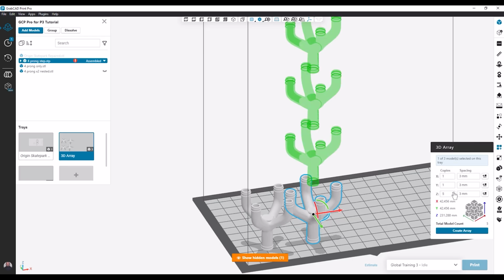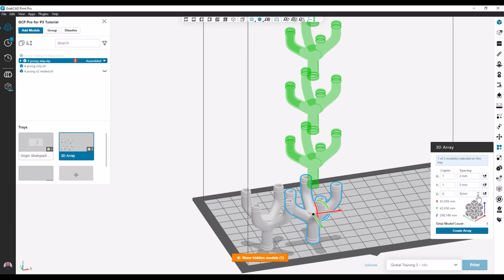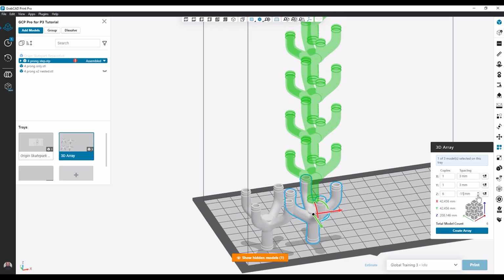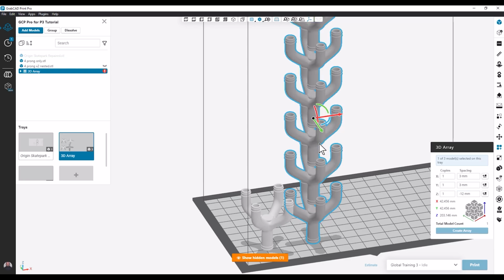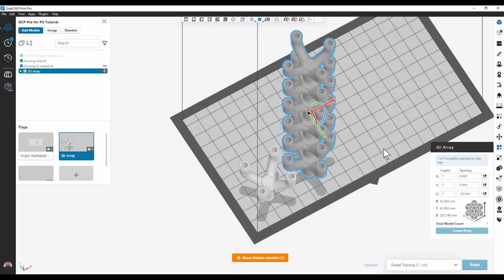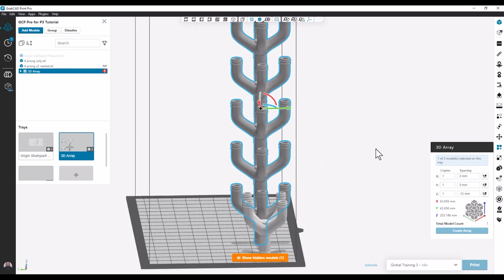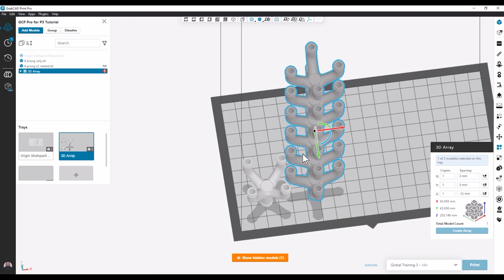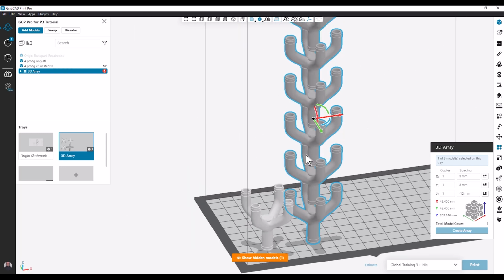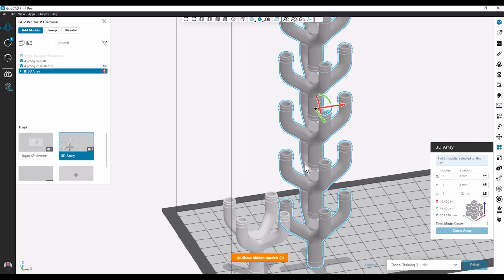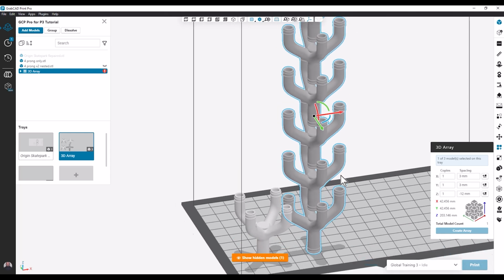Notice as the array is created using the step file, when we begin to rotate and navigate around the part, that our RAM usage on the computer is much greater. Our graphics have slowed considerably just by creating an array with the step file.